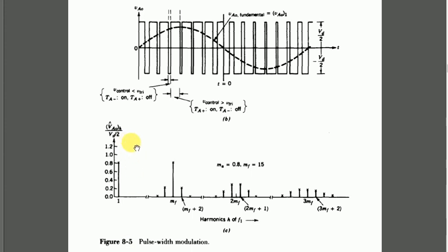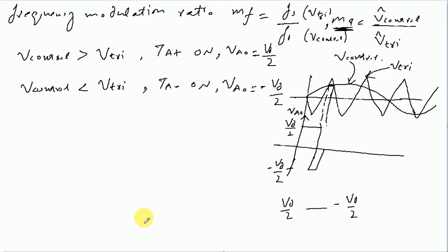One more thing you need to take notice of is that all these magnitudes are normalized by a factor of Vd/2. By normalization, we mean that all these values have been divided by the term Vd/2. From this we can see the peak amplitude of the fundamental frequency component, which for the remainder of the discussion will be represented by a particular variable.